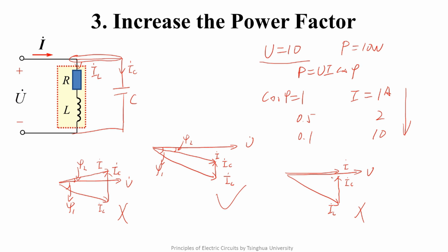Why is it unfavorable to compensate to the resistive state? That's because the work of the actual circuit is not as we imagined, static and constant. The connection and disconnection of the load is random. That is to say, the active power of the load probably changes over time. During a certain time period, if the power factor angle seen from the port is compensated to zero, then sometimes it's likely to change into capacitive and it might be resonant. These are the two main reasons why we adopt this compensation.